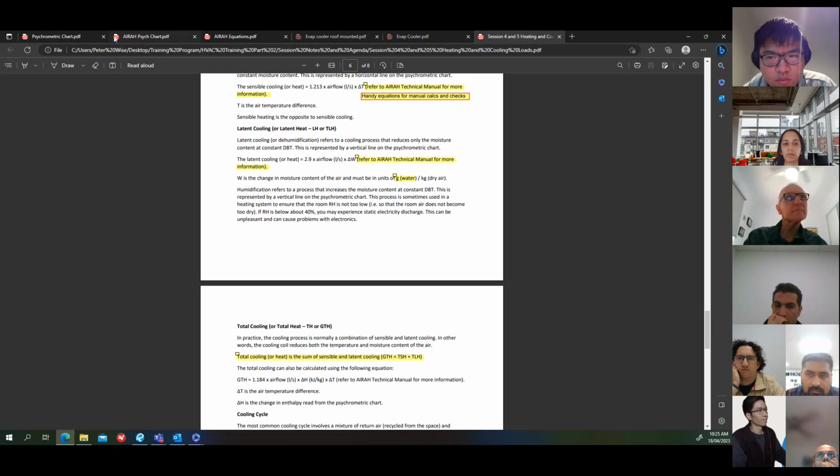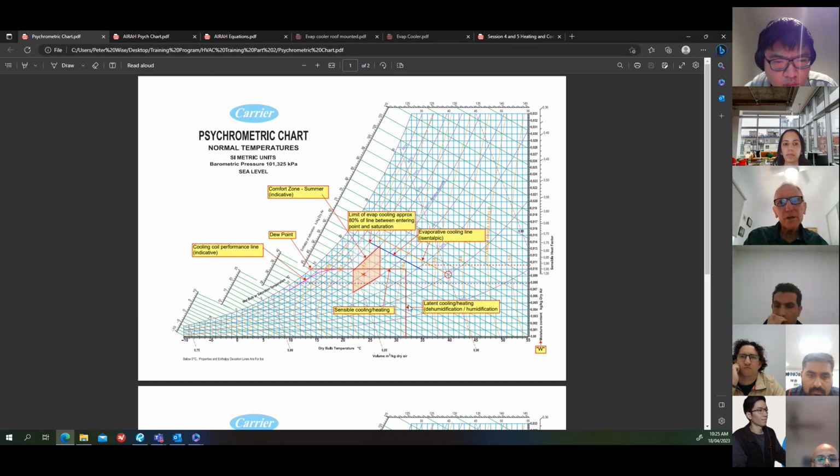So you'll get a combination of the heating, but also you're moving up this latent heat line. So in effect, you're getting an oblique line, such as this one here, for instance. You're heating, but you're also humidifying. I hope that makes sense.